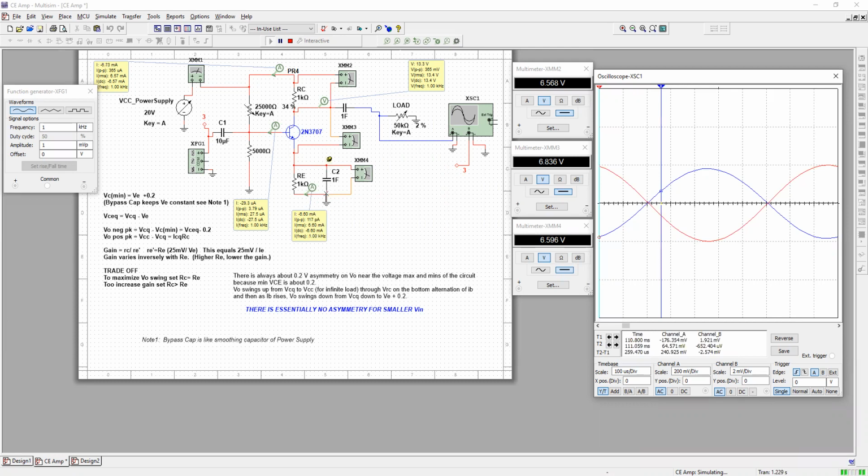Now that is going to allow the voltage of the collector to rise because more current is flowing. But it's not going to allow the emitter to feel that increased voltage. It's all being shorted out to the second capacitor here. And when that voltage falls, because the current IB falls, this is going to discharge into the emitter, which keeps the emitter constant still.